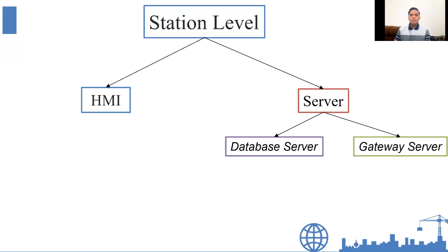The switching process of the HMI can be done if it is in a local general position. Standard HMI displays on SAS consist of, number one, system overview, overall single line diagram, bay single line diagram, AC and DC distribution system, event list, alarm list, common alarm, and trending.